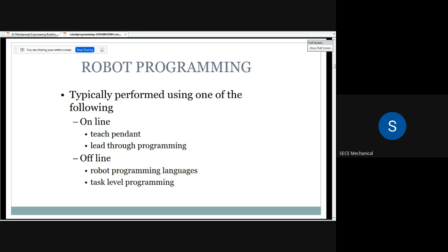Move up, move in the x direction, move in the y direction, and move in plus z and minus z directions. To give this movement I am using a tab, right? In the right corner of the laser cutting machine there is a joystick-controlled control unit. Now imagine a similar control unit. I will show you one video here. If I am using that kind of control, that is called a teach pendant, right?